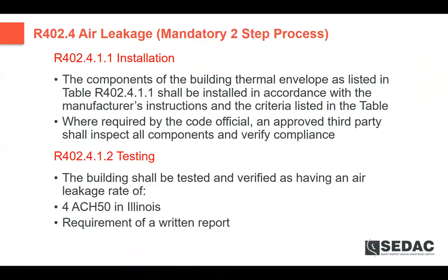So in the code, our 402.4 air leakage is mandatory, and it's a 2-step process. We have the installation, where we have to pay attention to the materials we are using and how those various materials are attached to one another so that they will be resilient and robust and not separate over time. And then the testing. And the testing is done with a blower door.